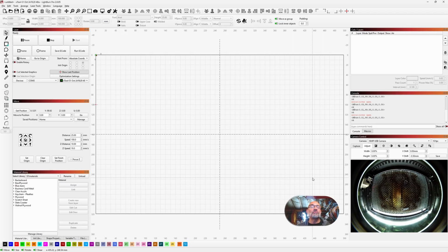What would I do if, say, you have to do a run of 50 blocks or 20 blocks, whatever it is? You put a piece of scrap wood at that level, you do a quick test engraving. If it's a line, great. If not, you go through and you just adjust the X shift and Y shift. In real time, you see the adjustment on the screen. Once it's done, start engraving. It's very, very easy. Again, I really don't have to do that.